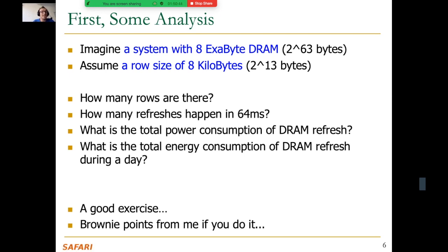And this is one of the potential benefits of non-volatile memory like we've discussed in the previous lecture. If you have phase change memory, for example, non-volatile, you don't need to refresh it. Now, I'm not perfectly correct when I say that, but you don't need to refresh it as frequently as DRAM. But we will talk about why you may need to refresh it later on when we talk about emerging memory technologies. There are other reasons why you may need to refresh it.